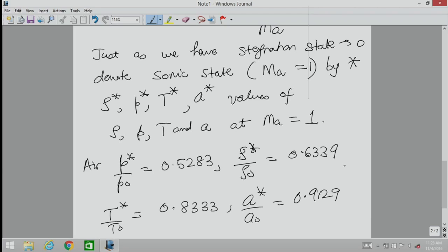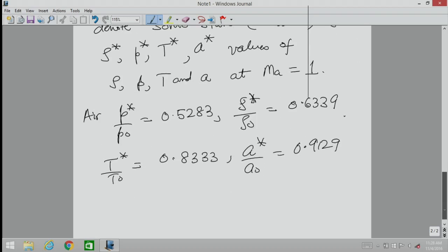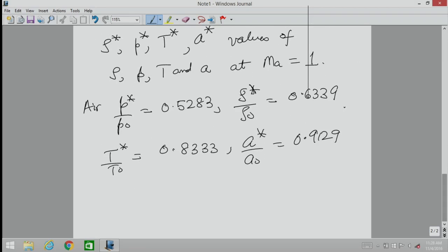It is an isentropic flow, you can get those values from the graphs, but it has not reached the sonic state at all. But still I can define a star state for that flow. So the sonic state could also be taken as an ideal state, and the role of that will come in when I discuss further things. Just as the stagnation state is there, it may or may never reach that value.